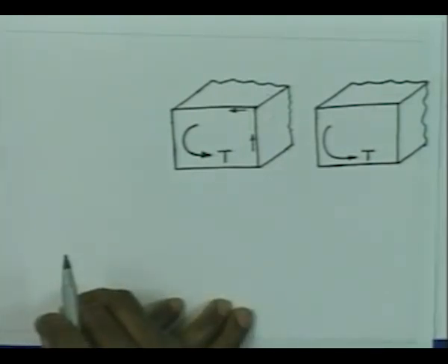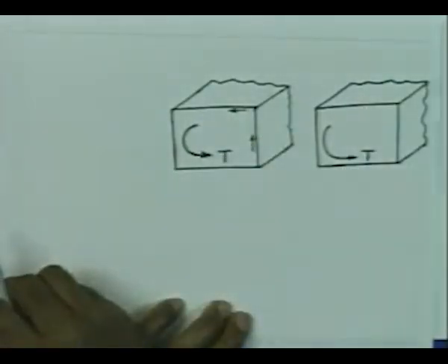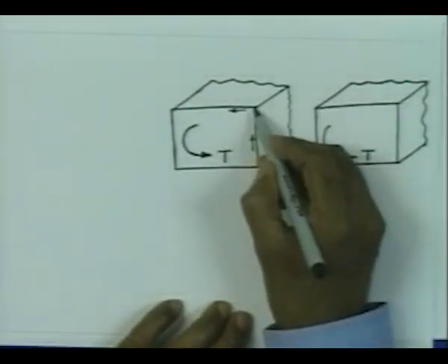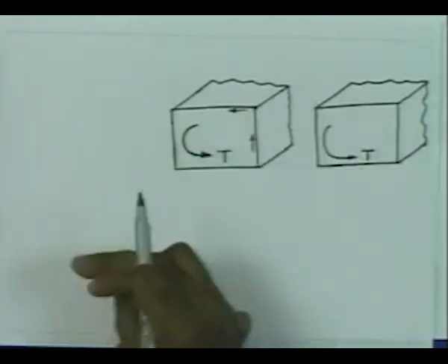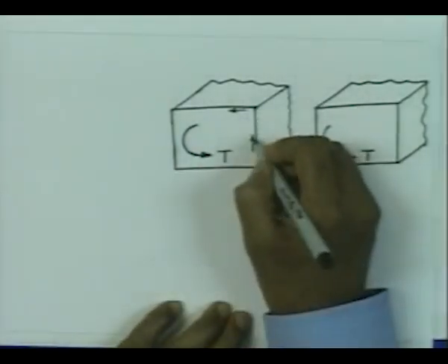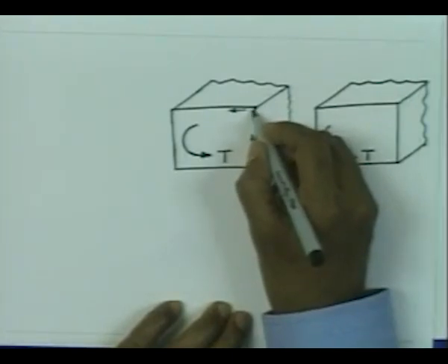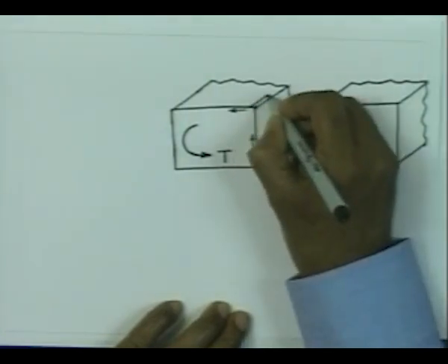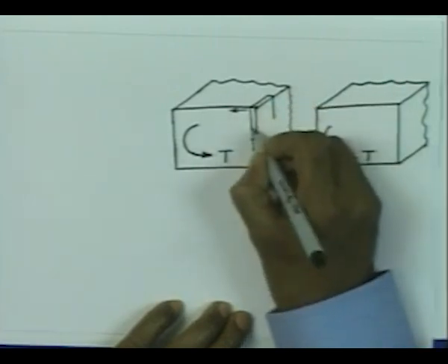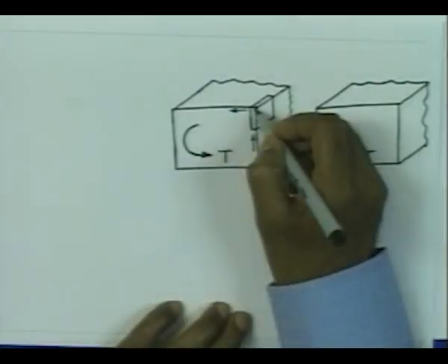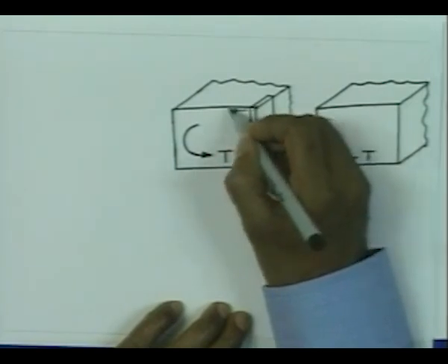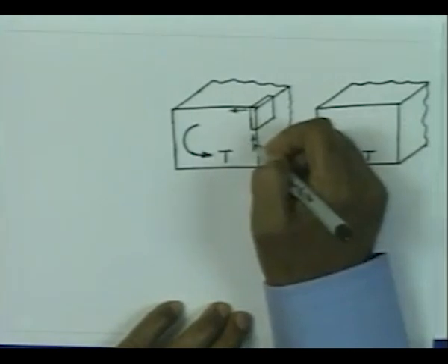Now, I would like to give you the answer from the consideration of the membrane analogy. If you now think of the membrane attached to this boundary and inflated from inside, the boundary deflection of the membrane is going to be 0 there, in the direction out of the cross section. We know for sure that the stress acting perpendicular to this boundary, so just concentrate on this element located here, the stress acting on this area is going to be directed vertically upward, and that is again related to the slope of the phi surface in this direction, and since phi is 0 all along, the slope is 0, therefore, this stress is 0.